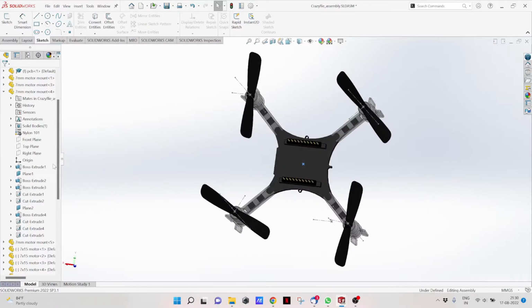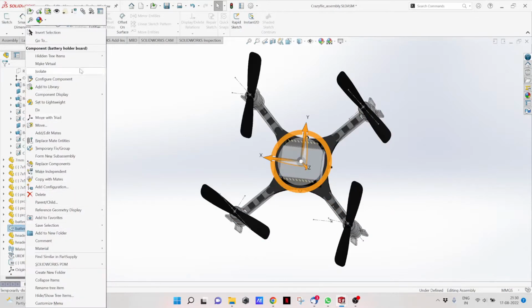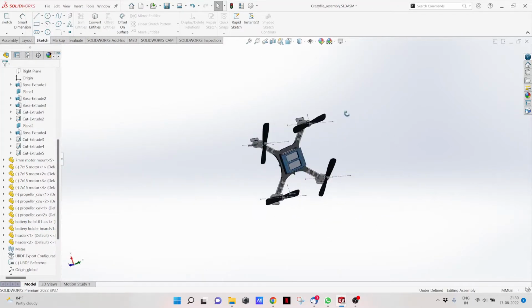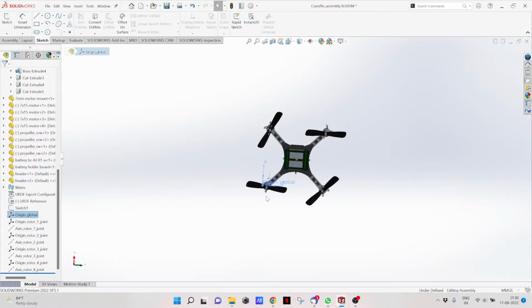Now you can also unhide the components. Okay, done. So now you can see the sketch here at the CG, but this sketch point is actually at the end of this entire tree, so we'll have to shift this to the beginning of the axis systems here. Okay, so now this point is accessible by all these joints, links and axis systems. So now we can start with the proper assignment of the reference system.